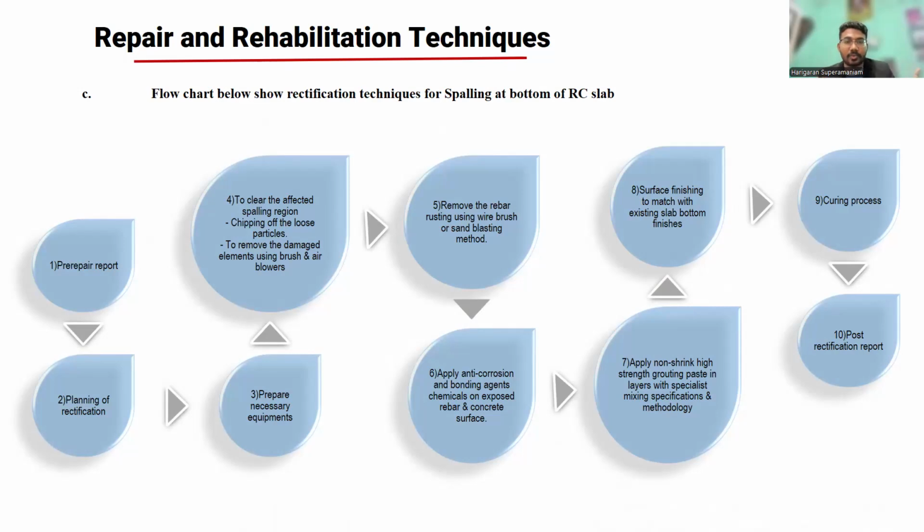Before that, I just would like to say that this repair is basically post construction. Okay, so it would be better if, as a designer or contractor, we consider preventive measures, like using corrosion inhibitors, waterproofing and so on, whatever preventive measures that can prolong the serviceability or durability of the concrete and reduce the maintenance. This is what I would like to highlight as info from my side.